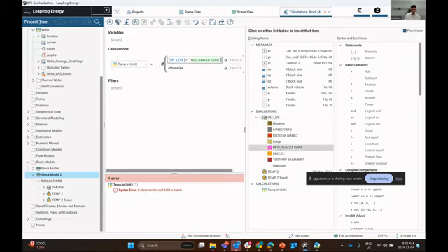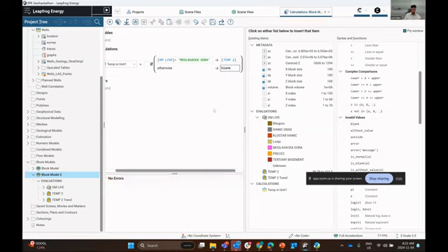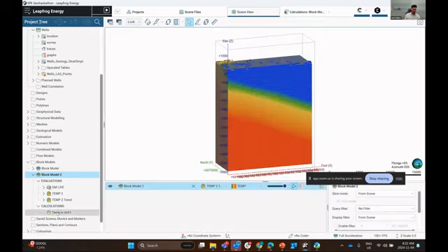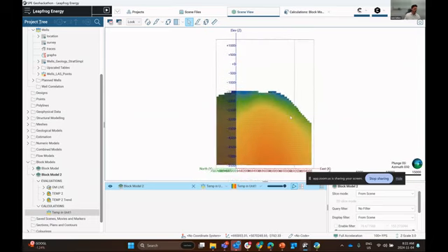Let's just say this pink unit right here. So if geologic model equals this pink unit, then we'll return the results from temperature 2. Otherwise, we'll return a blank. And I realize that this is quite quick, but this is just a quick overview to give you some inspiration about some of the things that you can do with this calculator. If you drag and drop this object in the scene now we can look at the temperature distribution that's constrained within that unit that we've defined.